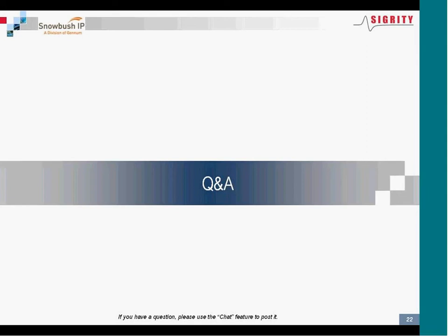And again, the modification we did to the model is very slight. Really, the only thing we changed within the models was the getWave function, and the function call itself for the getWave has not changed. The only thing that has changed is that the pointer that was used to pass in the parameters out can now be used to both generate output data as well as read in results. So we basically just made that pointer connect to a bidirectional register instead of an output-only register. But the function call itself is exactly the same, so it doesn't break anything.